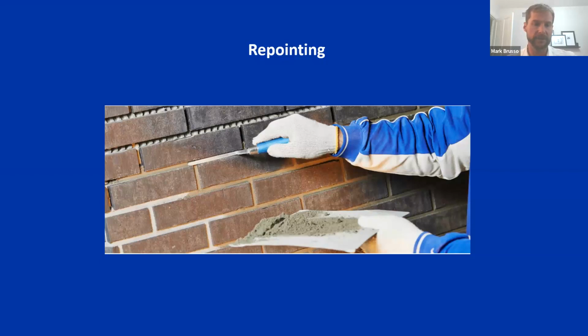So keeping an eye and being somewhat knowledgeable of your mortar and grout standards is also important in the whole big scheme of things. So keep in mind, keep an eye on those mortar joints on your restoration projects, because the cracks are telling you something needs to be done.